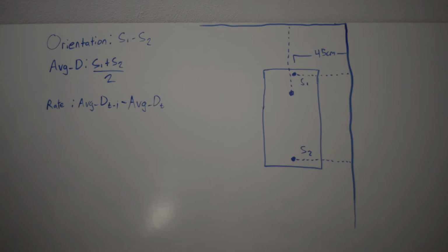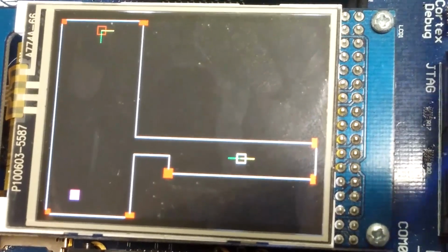Position determination was accomplished by matching the left and right turns of the rover with the left and right turns on the map given to us. The rover continues to follow walls until it finds a series of left and right turns that occur only once. At that point, the position determination algorithm knows exactly where the rover is.